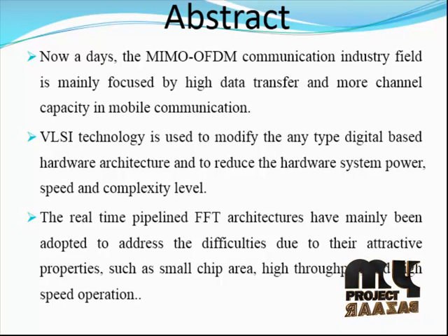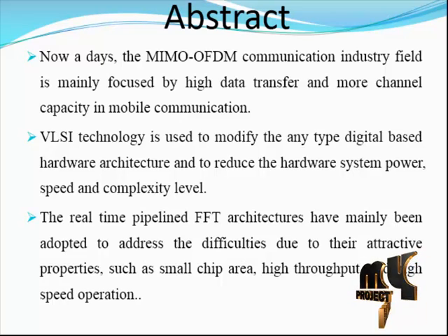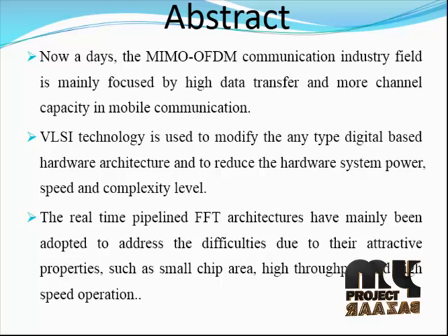An efficient combined single path delay commutator and feedback Radix-2 pipeline fast Fourier transform architecture, which includes log2 N minus 1 SDC stages and 1 SDF stage. The SDC processing engine is proposed to achieve 100% hardware resource utilization by sharing the common arithmetic resource in a time multiplexed approach, including both adders and multipliers. Thus, the required number of complex multipliers is reduced to log4 N minus 0.5, compared with log2 N minus 1 for the other Radix-2 SDC SDF architectures.